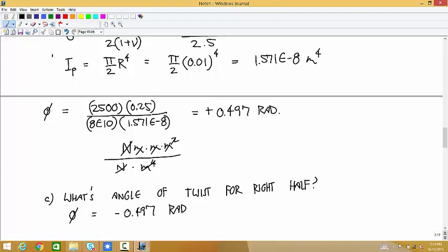Does that also hold when your twist is off the center? Your angles should also add up to 0, if you're putting torque not in the middle? Yeah, so if the bar is fixed on the two ends, then no matter what loads are applied, they have to add up to 0 twist, no matter what location. That's just a property. That's just saying that they're fixed in a way that you can't move them. You can move the stuff between them, but you can't move those 2 points.